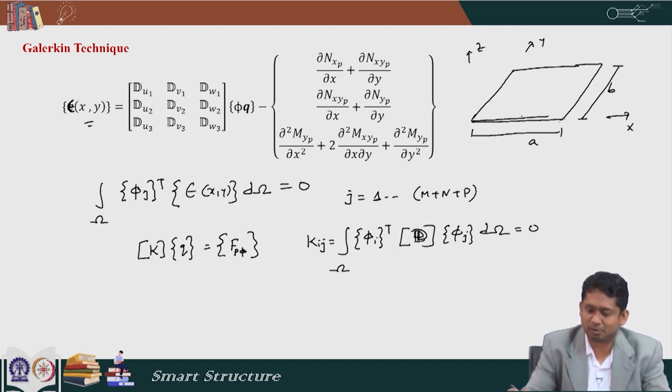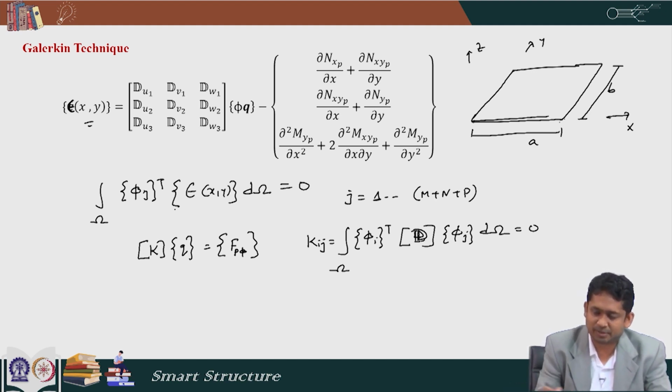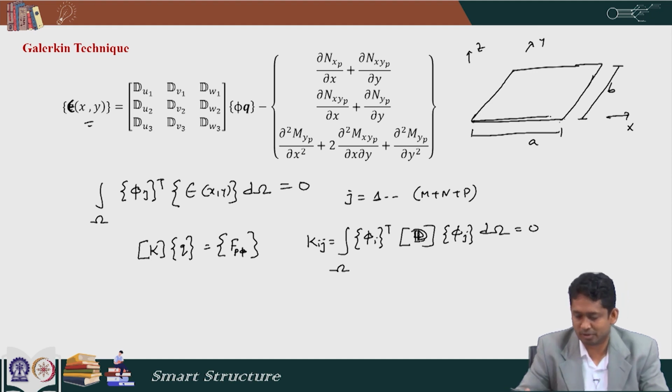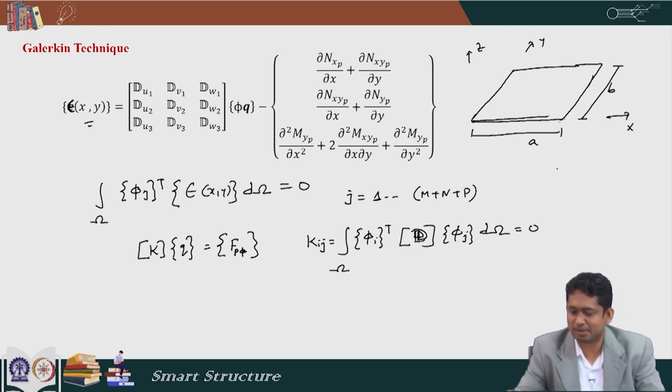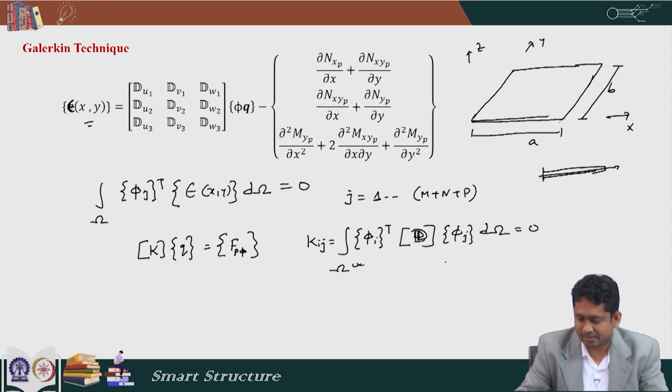So, the thickness is not coming into the picture. So, here we are dealing with only the 2D surface domain of it. Just like that, for a beam problem, we got rid of the thickness by integration and we dealt with the governing differential equation only on the x axis. Here it is spanned by the x and y axis, and that is our capital omega.